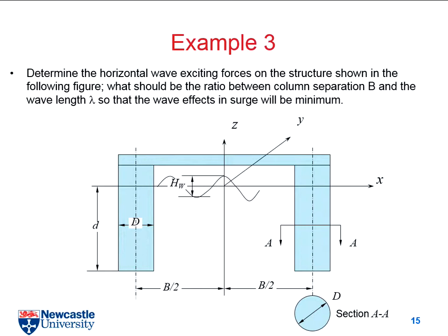Excuse me, what is the criteria to decide whether or not we approve? Usually, when you apply Morrison equation, we use D or L against the wavelength, and if the ratio is smaller than 0.2, it means we can say it's small. But in my part, I would stress, if you have a vertical one like this, we always use the integration because it's quite long. But if it's a horizontal one like this, it's okay. But it's in terms of horizontal response.